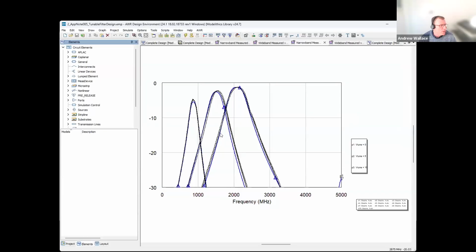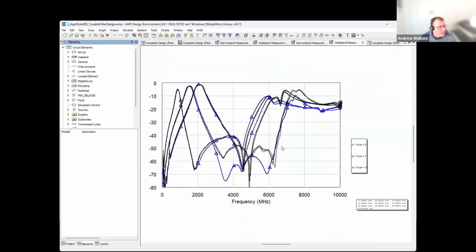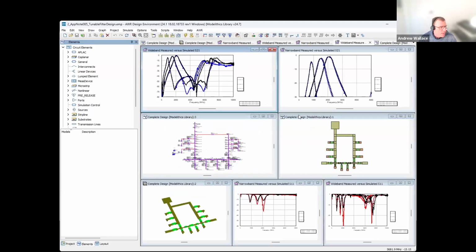And when simulating this, just as Chris alluded to, over three different simulation voltages, 0, 6, and 16 volts, you can see the accuracy on the solid blue traces here, tracing and emulating the measured data in the dotted black traces. Even quite a long way out of band. Appreciate they're not following exactly the depth of these traces here, but below minus 50 dB is incredibly high accuracy for this type of filter design out of band, and they're following the correct trajectory and shapes.